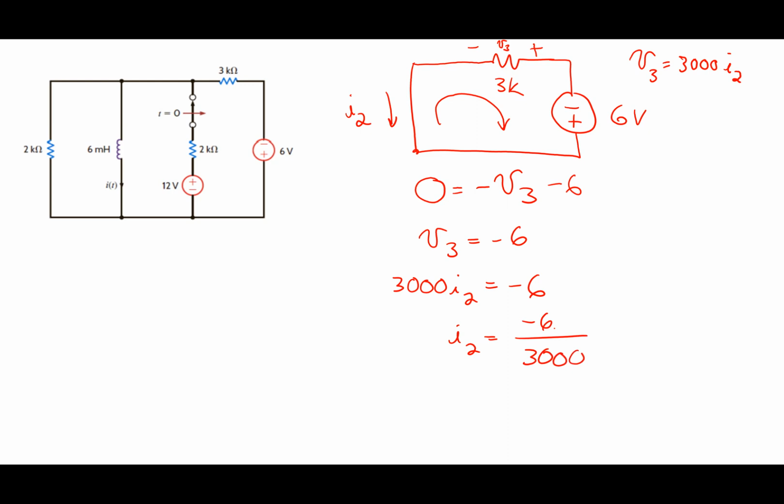Okay. Now, that negative sign bothers people sometimes. What's the negative sign mean? It doesn't bother me at all. Don't let it bother you. It just means that it's going the opposite direction of the arrow, right? Which sort of makes sense because, if you look at this, current would have to be leaving the plus node of that battery. It would have to be going against that arrow. That's okay. All right, totally okay. It just means it's going a different direction than what I wrote here.